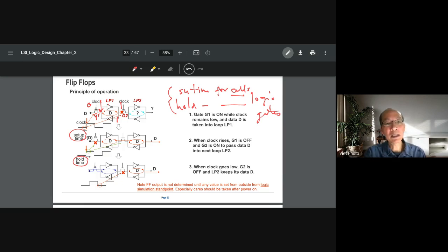You will see later there is another thing people talk about. I think I already mentioned that setup timing is the setup check, related to the frequency or the target frequency. Here, when we talk about the cell, it is setup time for the cell and hold time for the cell. There will be setup time for the design too, which is different from this. Along the way I will explain that, but for now you know it's only setup time for the cells.